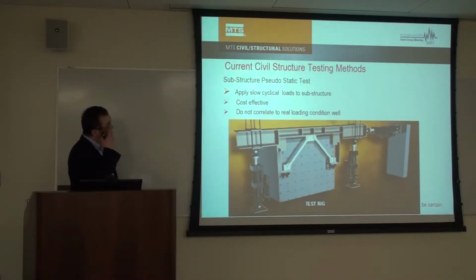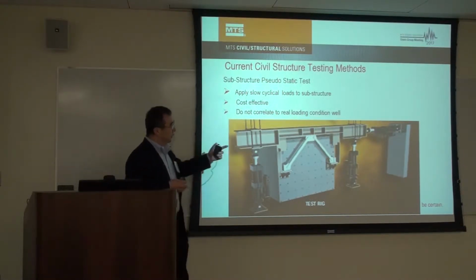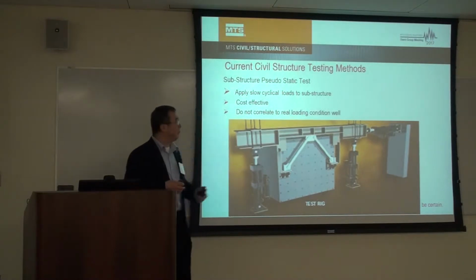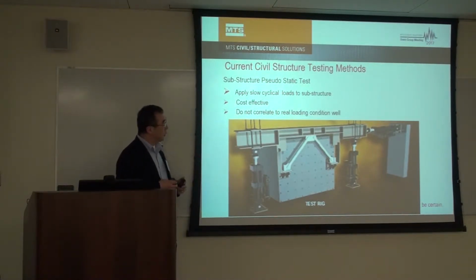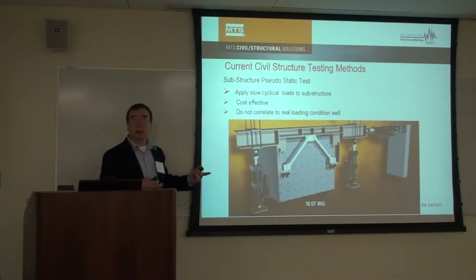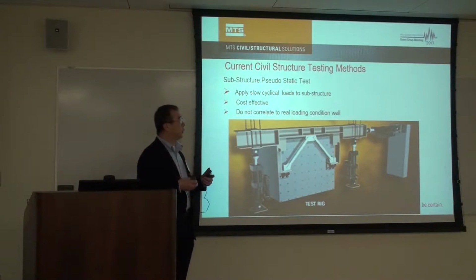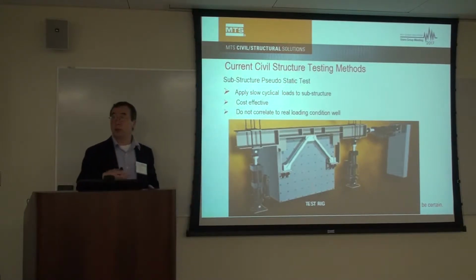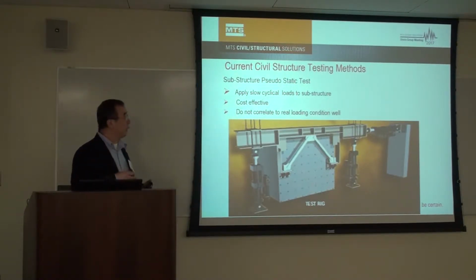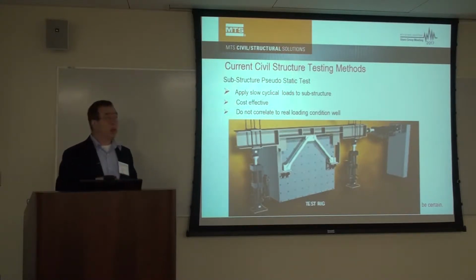Another test very commonly done is a pseudo static test, where you do a test on a component, not the full structure, and the loading is fairly simple: a triangle wave, the first 3 waves, then you increase the amplitude for another 3, and increase the amplitude another 3 until it fails.